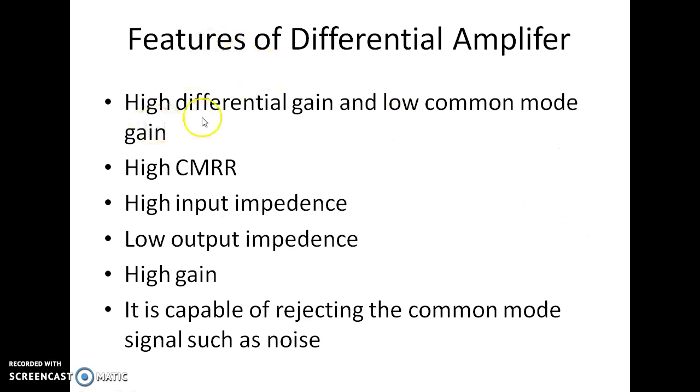It consists of high differential gain and low common mode gain, high common mode rejection ratio, high input impedance, low output impedance, high gain, and it is capable of rejecting the common mode signals such as noise.